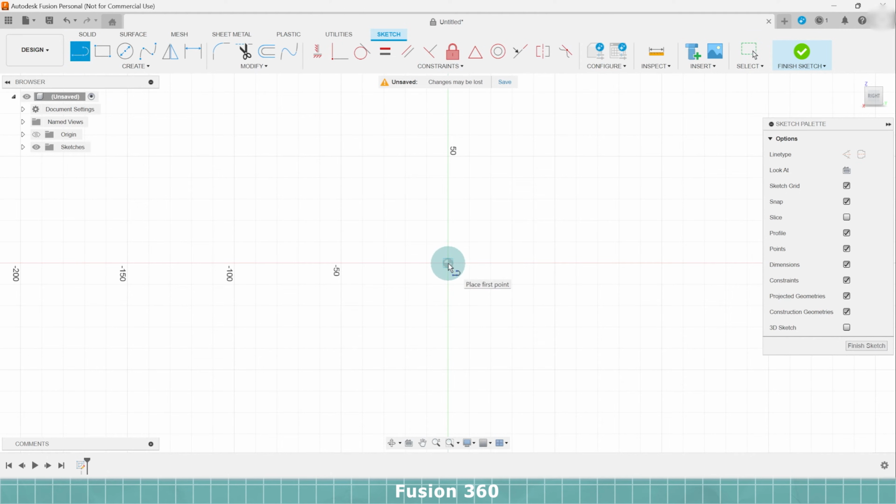So I start out by selecting the line option, and this is under the Create Sketch button found in the Solid tab. So I'll start by clicking the origin point, moving the cursor so that it snaps to be horizontal, then typing 93mm and clicking Enter. I'm just following the lines and dimensions from my sketch and roughly guessing the angles of some of these lines. Don't worry, it doesn't need to be exact right now, and we could adjust the angles afterwards if necessary.